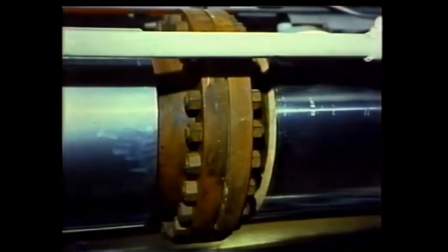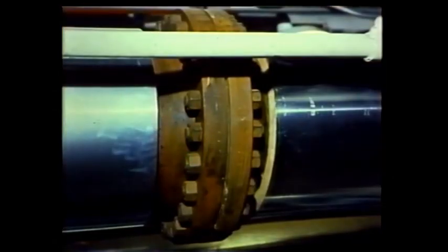In addition to the flange, some pipes are just threaded together with a union, nipple, or coupling. These types of simple connections are found mainly on low-pressure systems or on very small piping, 2 inches or less in diameter. On large pipes and in high-pressure systems, pipe connections are usually welded or bolted together. The type of connector, threaded, welded, or bolted, will depend on the kind of service the system's used for. When replacing a connector, always install the same type as the original.